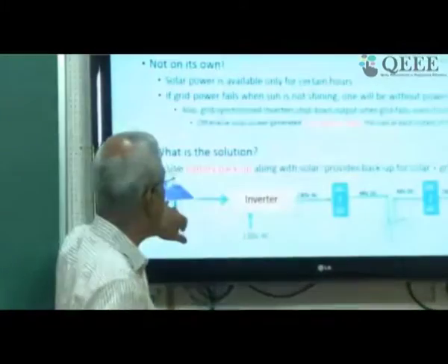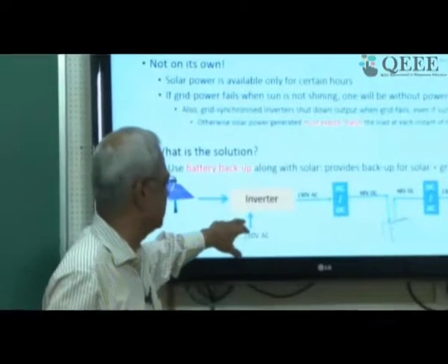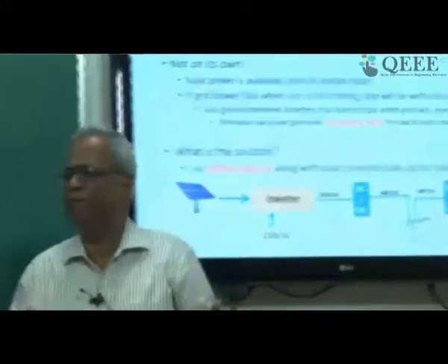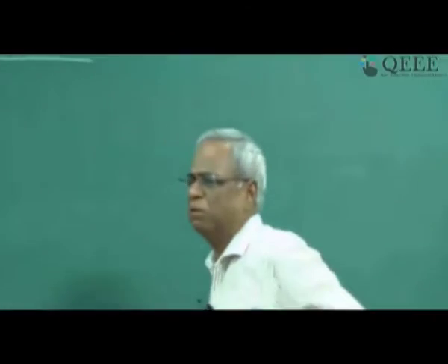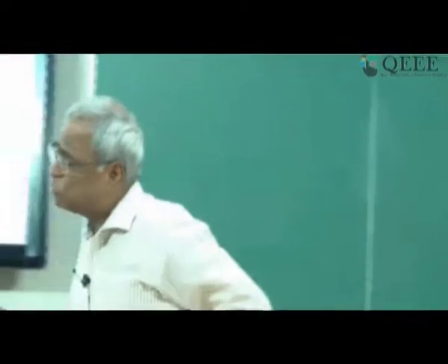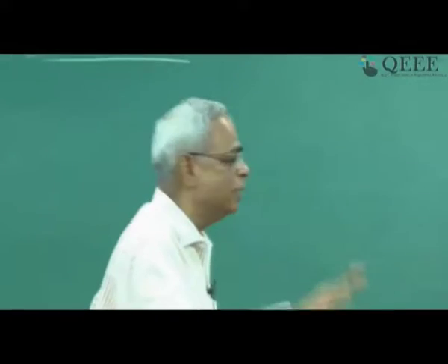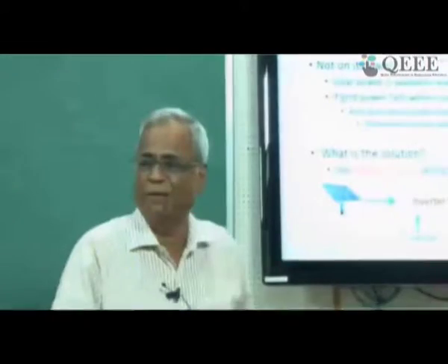If it's a larger panel, if it was a 10 kilowatt panel, you could have got this at 97%, 96%. This could have also been done at 5%. Your losses would have been only probably 15% overall. Plus battery, 10%, 25%, you still would lose things, but at least it is manageable. Maybe 20%. You can overall reduce it to 20% if you do 10 kilowatt.